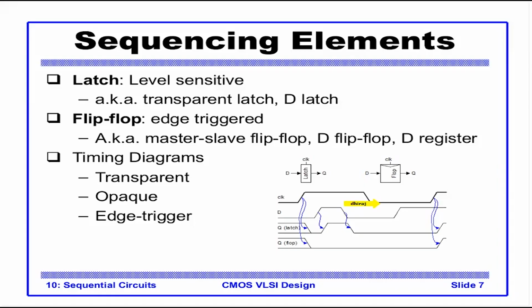On the other hand, a flip-flop, whenever the clock goes from 0 to 1, that is during a positive edge, in a positive edge triggered flip-flop, whatever is on D passes on to Q. So now at this moment D is 0, so Q goes down to 0. The blue arrow shows the logic and the timing effect.